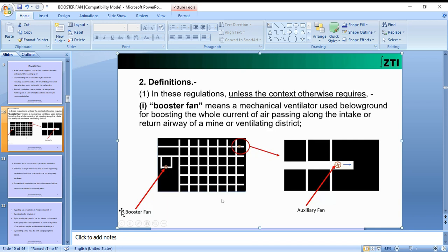The fan, when circulating a large quantity, generates less pressure. The reduction of the quantity circulating through the unboosted subdistricts, due to a large booster in one split, can cause stoppage of air current or even reversal of air current in other splits, particularly if the trunk resistance is high compared to the resistance of the split.